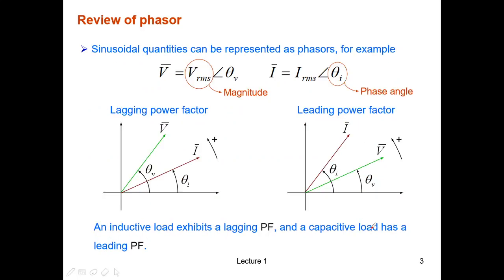Because we are using sinusoidals, we can also use phasors to simplify the way we express this. As you can see, the average power doesn't have omega at all, and therefore we don't need to use the angular frequency when we calculate average power. We only need the RMS value of the voltage and current, and also the phase of those phasors. So a phasor in this course is defined with the modulus as the RMS value, and the angle is the initial phase angle, as you can see here.